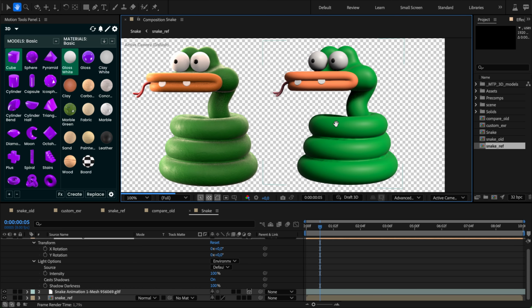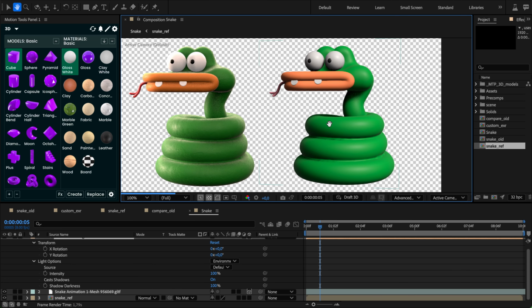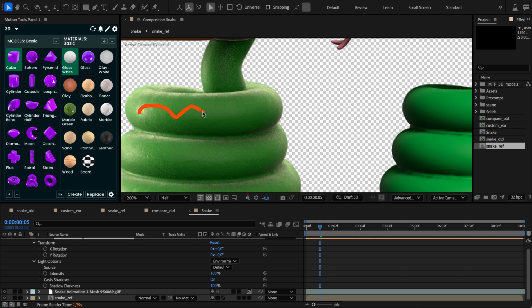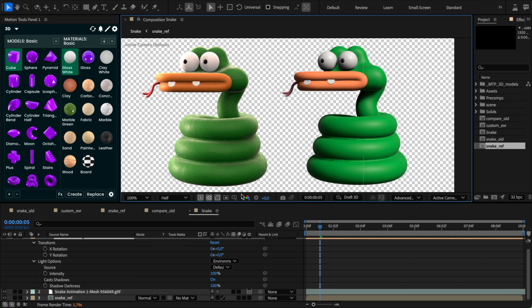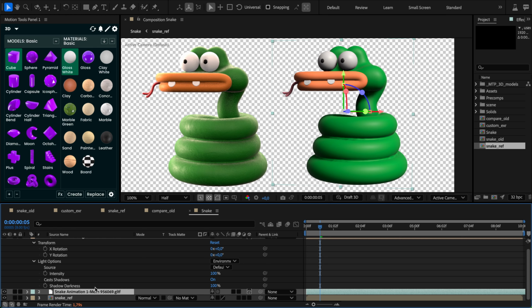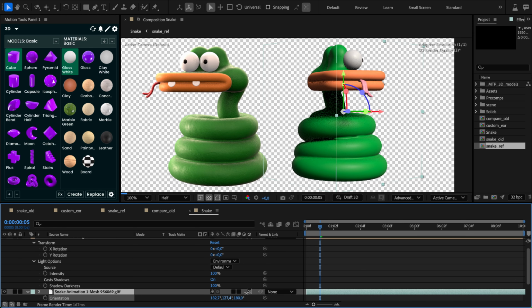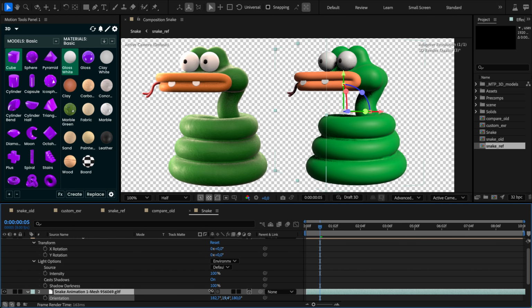So, to make our work faster, I'll make a few render adjustments. I'll set resolution sample factor to half. This means we will lose some small texture details, but overall the picture will remain the same. While working on light and shadows, this is acceptable. In the Fast Previews drop-down list, I'll activate Adaptive Resolution. This setting dynamically adjusts the resolution of the preview to speed up model manipulations.